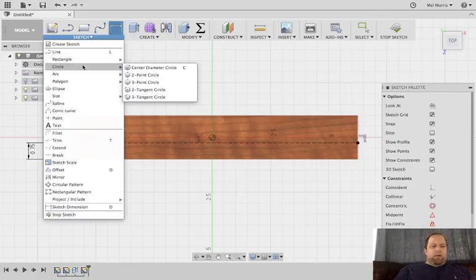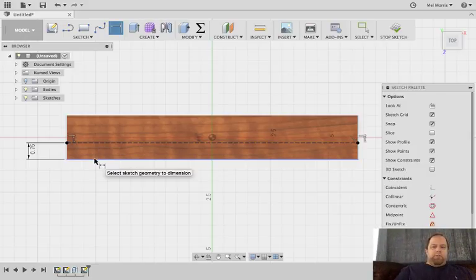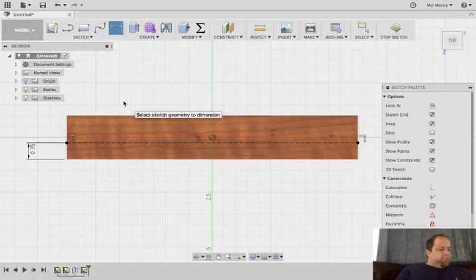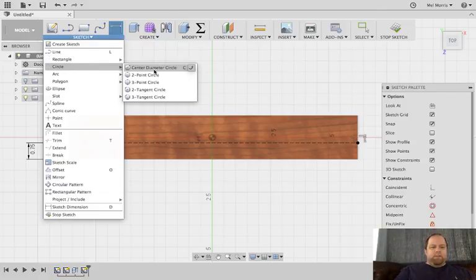So now I'm still in Sketch. I've created this construction line, a given distance from the front face. Because if you're looking at it from the top, this is the back, left, right, front. I think that comes across as being clear. So now I go into my Sketch button. There's other ways to get these, but this is the easiest way.